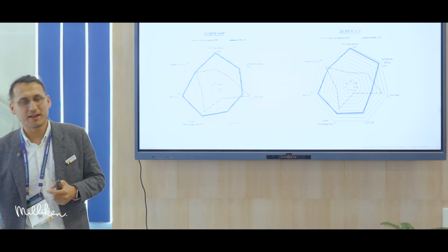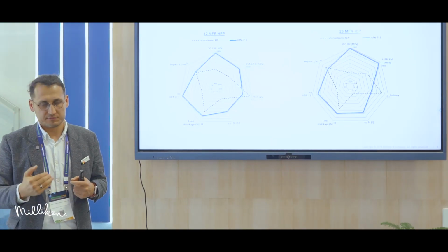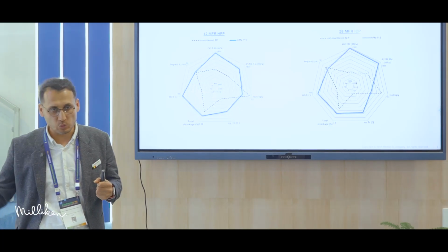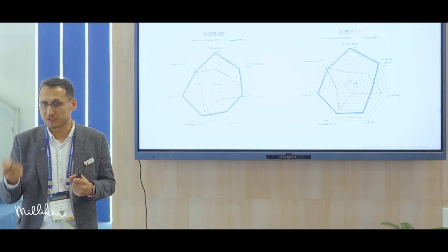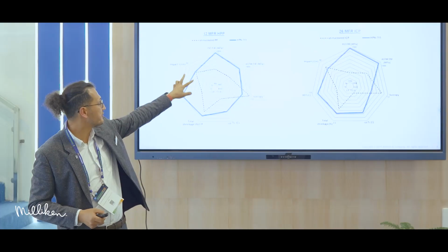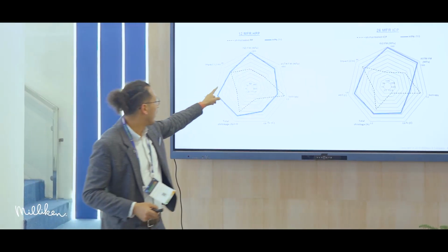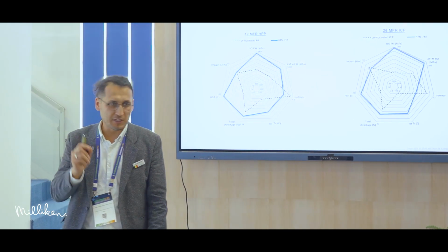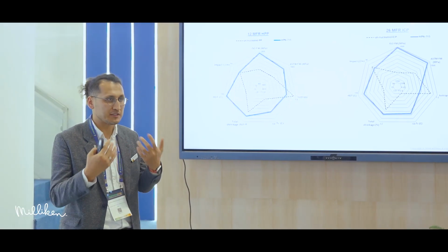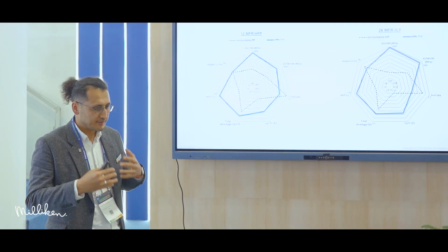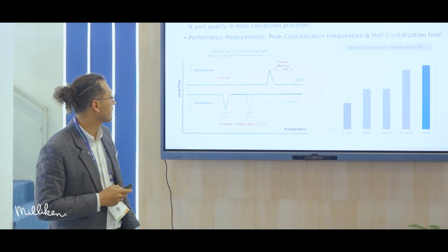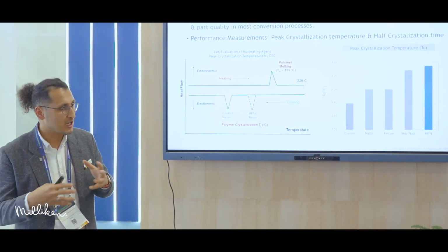Because if you want to have stiffness improve, you put a lot of, for example, cheaper filler like talc. It can improve stiffness dramatically, but at the same time, you lose your impact. The parts become too brittle. Now, with nucleator, you can increase stiffness, the modulus, significantly, while the impact is not influenced or influenced very, very minimally. So that is the benefit of using nucleator, because of the crystal growth that can improve the stiffness without impacting the impact performance.